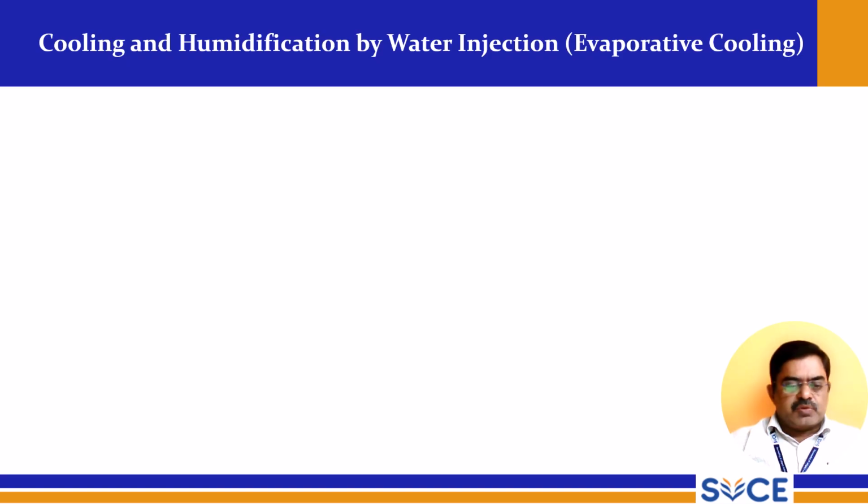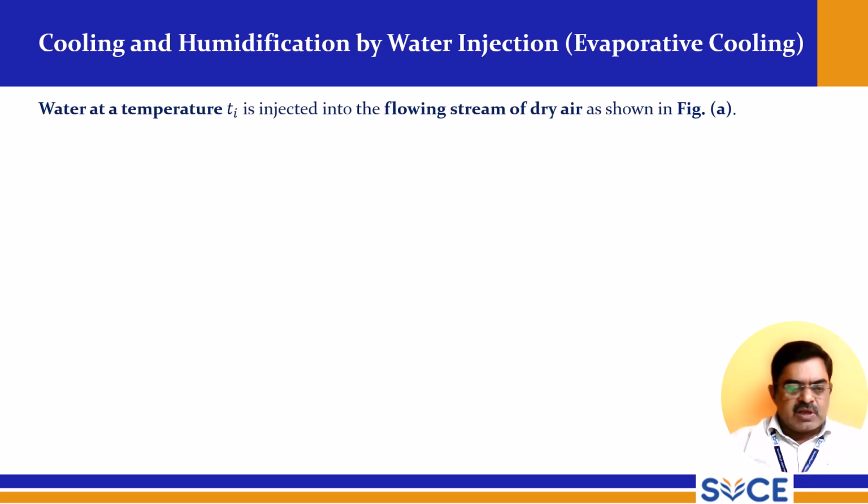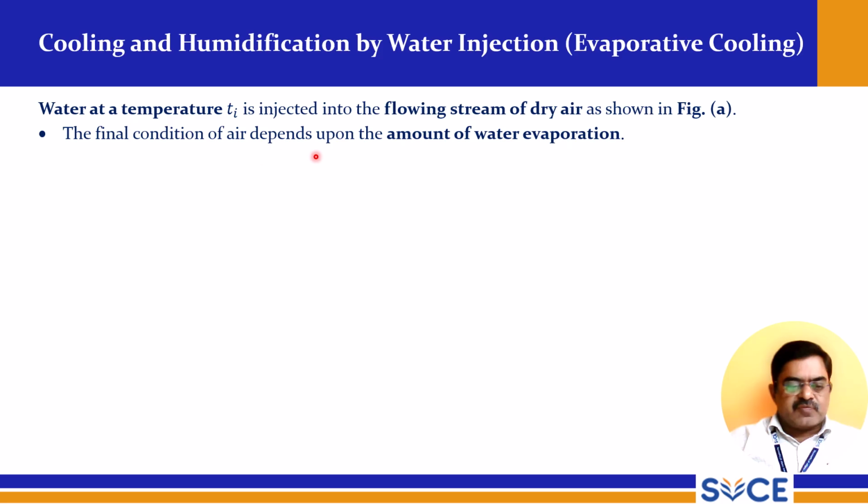So cooling and humidification by water injection, that is evaporative cooling. This is also known as evaporative cooling. Water at a temperature Ti is injected into the flowing stream of dry air as shown in the figure. The final condition of air depends upon the amount of water evaporation.